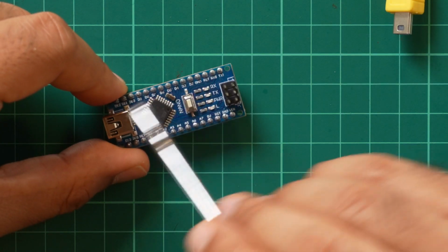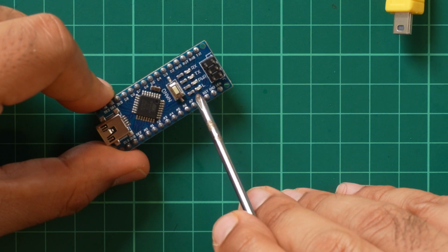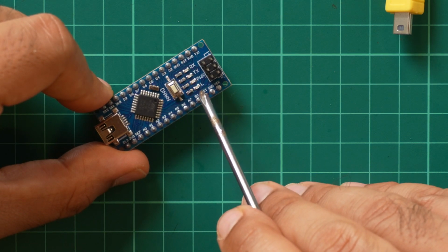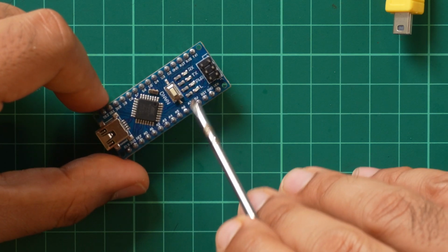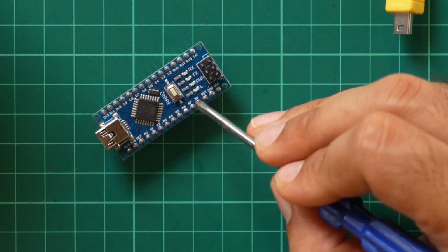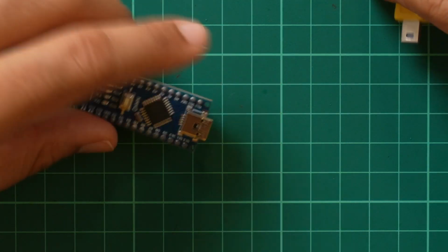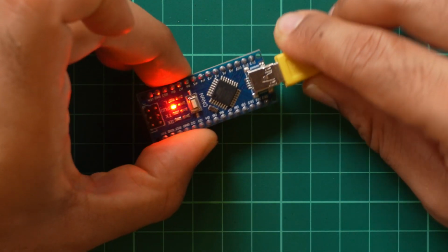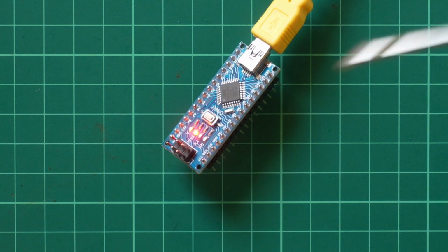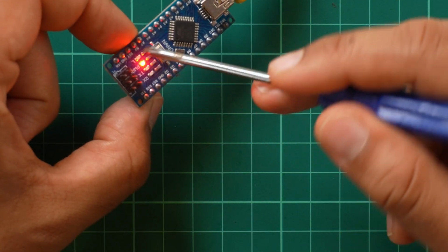Now, if you look very carefully on your Arduino Nano, there is a LED labeled L under the power LED. This LED is a programmable LED. So what that means is we can actually program this LED to turn it on and off the way we would like. And that's exactly what we're going to do in the first program. We're going to power up this Arduino Nano, and after that, we're going to try and program this onboard LED L to turn on and off once every 1 second.